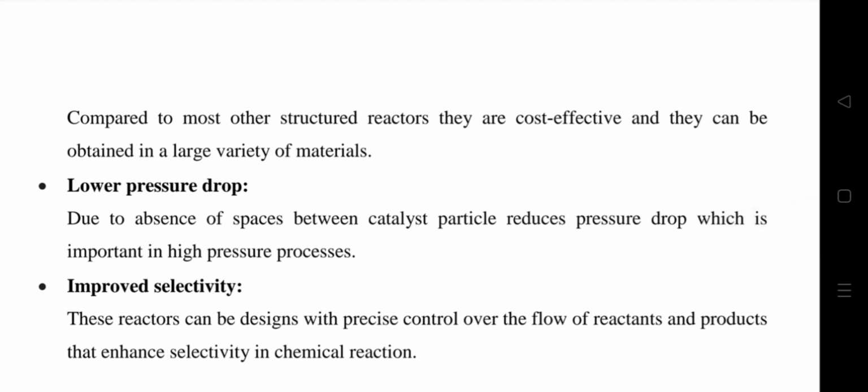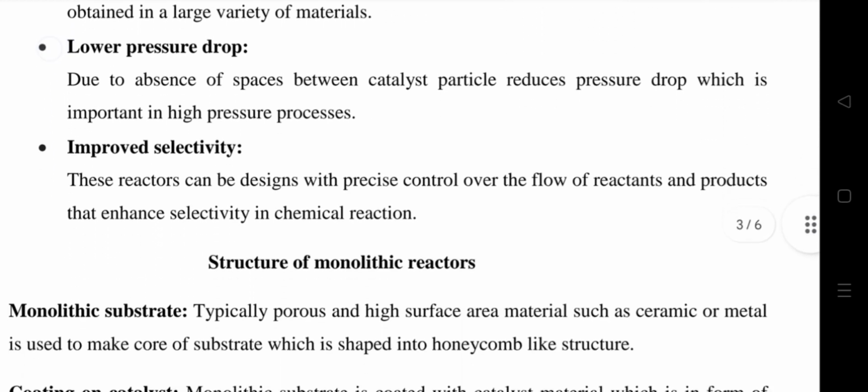Low pressure drop. Due to the absence of spaces between catalyst particles, the pressure drop is reduced, which is important in high pressure processes. It improves the selectivity. These reactors can be designed with precise control over the flow of reactants and products that enhances selectivity in the chemical reaction.